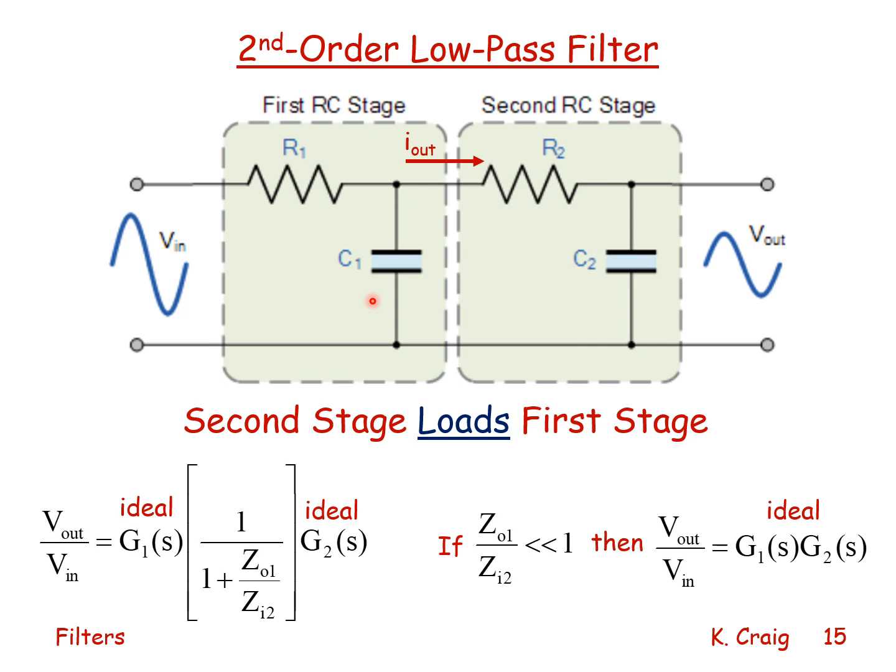The reason is that when I analyze a single RC low-pass filter, I assume that it is unloaded, that the current flowing out of the RC circuit is 0. Clearly, for the upstage RC filter, there is current leaving the first stage and flowing into the second stage. The first stage is loaded. The second stage, if there is nothing connected to it, the output current will be 0, and this then behaves as an unloaded RC low-pass filter.